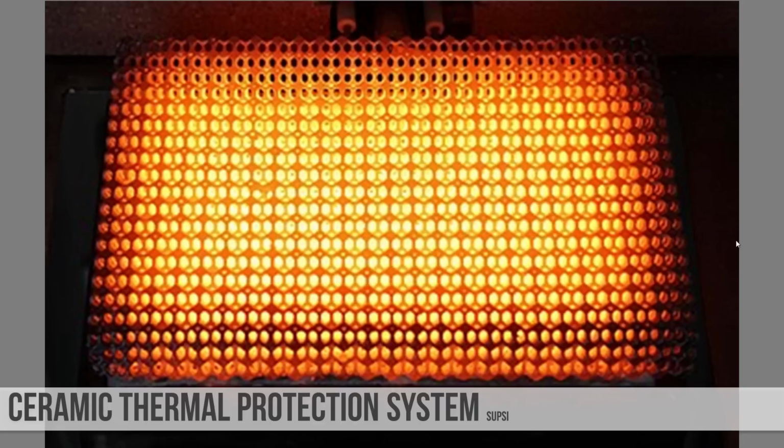One of the main applications that they're looking to implement these into is thermal protection systems for re-entry vehicles. What they're imagining here is a cellular structure that's not just a flat plate like what you see here, but actually conforming to the shape of a re-entry vehicle, surrounding the interior and protecting the inhabitants or whatever equipment is in the interior of that re-entry vehicle from the heat. I think this is a fascinating application. It's going to be something that really opens up new doors in terms of what was possible over the foam process with the 3D printing process.